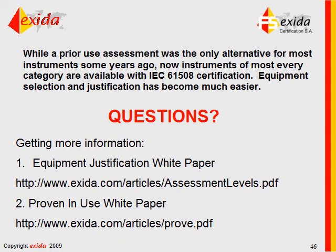You have a choice for safety integrity justification. You can buy certified products, or you can do your own self-certification program. The standard does not prohibit you from going either way. Most important thing, document your self-justification. Make sure if there's ever an accident, and if you're ever called on the carpet, you will have all your paperwork ready to go.